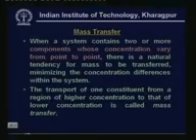So, mass transfer can be defined as the transport of one constituent from a region of higher concentration to that of a lower concentration. Why do we study mass transfer in refrigeration and air conditioning? Because in refrigeration and air conditioning we typically encounter several cases where mass transfer takes place. A typical example which all of us are familiar with is that of drying. For example, when you leave a wet cloth in unsaturated or dry air, the cloth becomes dry. So, what has happened? Water from the wet cloth is transferred to the surrounding air. This is one popular case of mass transfer.